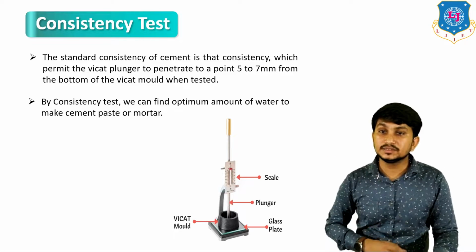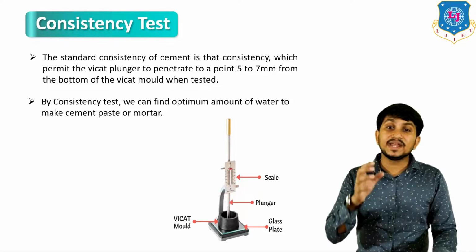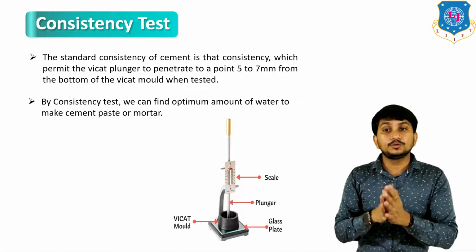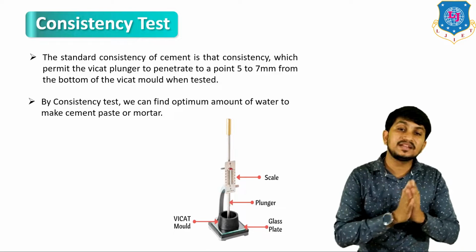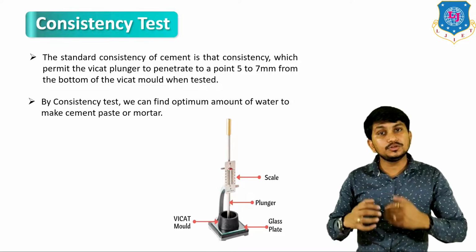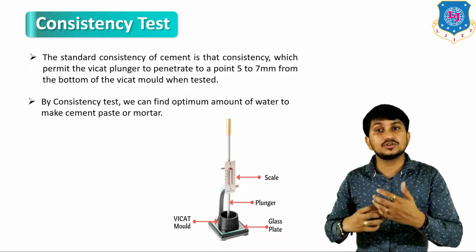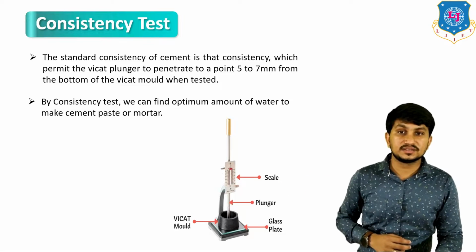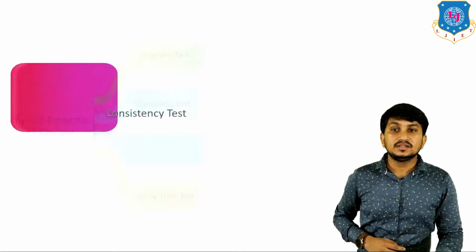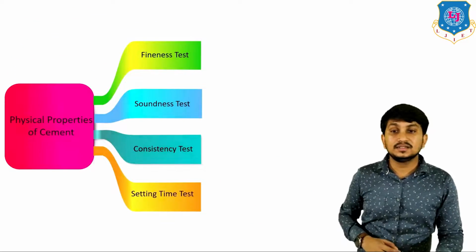By the consistency test, we can find the optimum amount of water to make cement paste or cement mortar. So you have to use different water cement ratios for this consistency test. That's all about the consistency test.